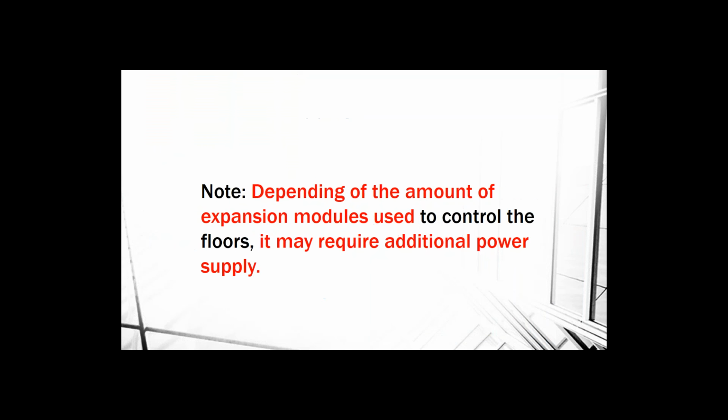The second note: depending on the amount of expansion modules we're going to use to control the floors, it may require an additional power supply. Please refer to your installation guide so you can do your proper calculation to know if you need to add power or not. Okay, so those are the two notes you need to keep in mind. Then we can move on.